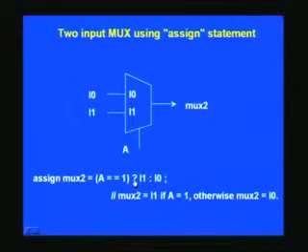The question mark is once again a mandatory thing, and for the mux, this structure at once reveals that it is a mux implementation. It has 2 inputs as we have already seen, and the first input that you write is not I0, please make a note of this. We have to write I1 first, followed by a colon which separates it from the other input. This is clear, I hope.